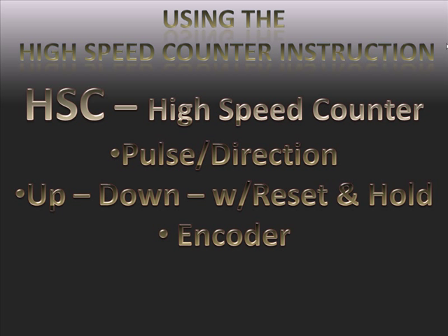With the count up and count down instructions in typical conventional use, they cannot increment the accumulator of a counter data type at a rate faster than the scan rate of the program. PLCs are synchronous. They gather the input data into the input image in the data table, then they execute the logic, they update the outputs, do a little housekeeping, and then update the input image again.